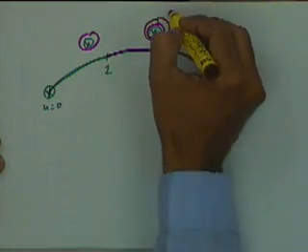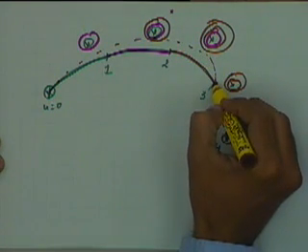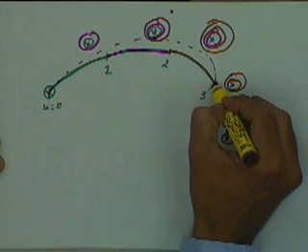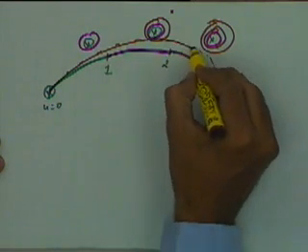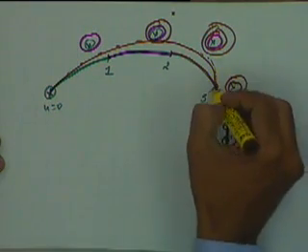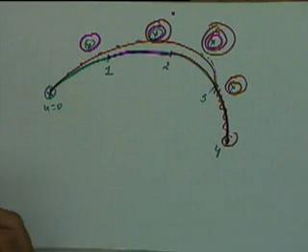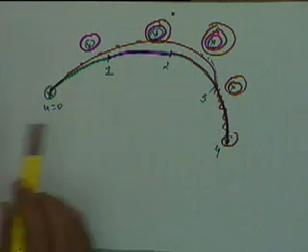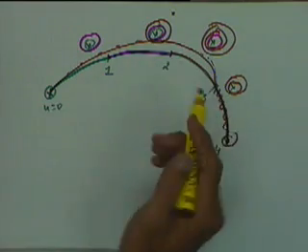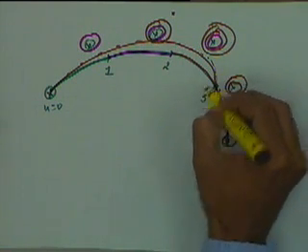So if this point is moved from here to here, my curve will probably get modified to something like this. It has to maintain C1 continuity here. So my curve would look like something like this. This portion of the curve will remain unchanged if I move this point. This is the first thing that is important in terms of the B-spline curves. We get a local control, the curve will get modified only in a certain range. This curve will be C1 continuous. The first derivatives will be the same here, that is, the slope would remain the same at this point.